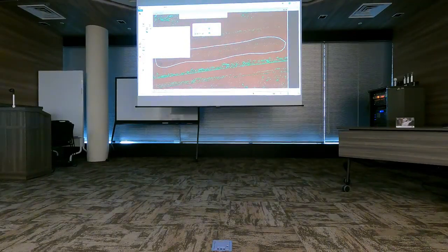For the boundary, I select 2D draped to surface. The other alternative is 3D used directly. But in this case, my bounding polygon is on some level. I want this to be draped to the surface of the point cloud, so draped to the top surface.